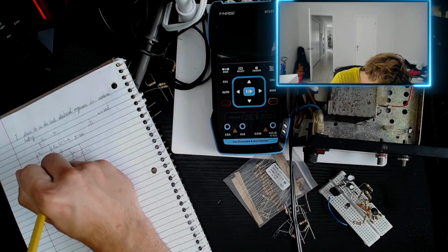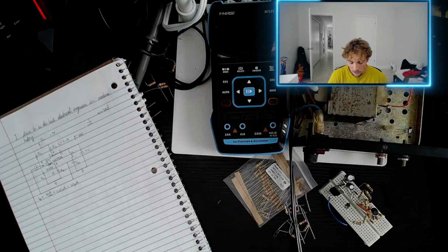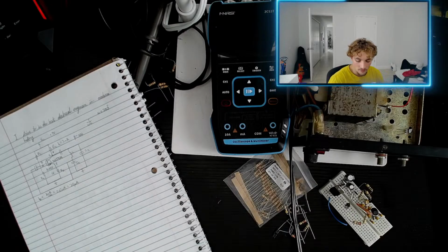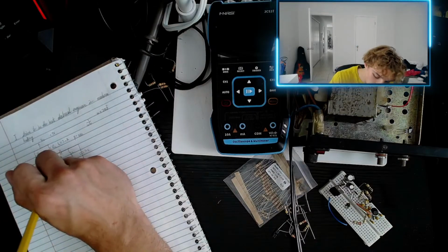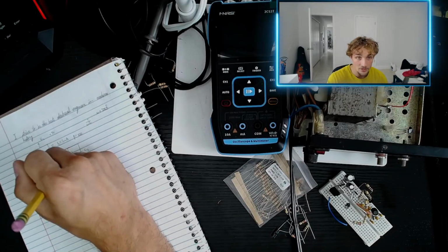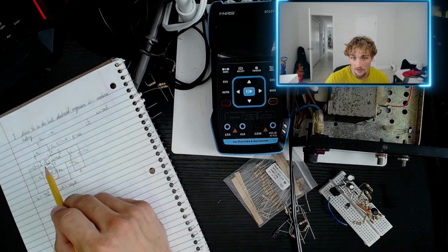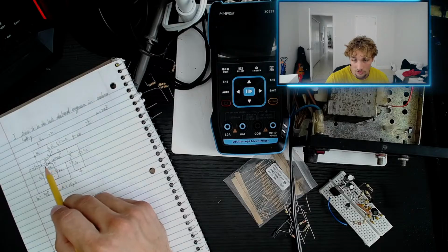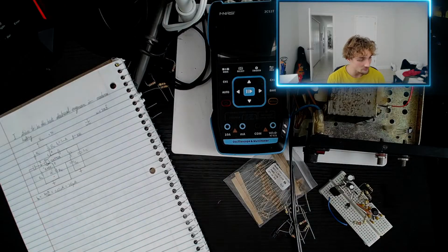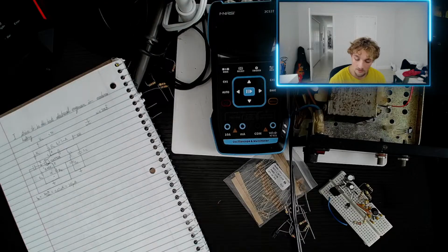Now, this reason I haven't fully come to a conclusion on. I don't know exactly why we want 1 volt here, but as we do our calculation, we might come to an understanding. So that's another assumption we want to make, is that we have 1 volt across the emitter resistor, right? So positive, negative here. We're having current flow in this direction. This is our emitter resistor, and our voltage across the base to emitter across our transistor is going to assume a value of 0.65 volts as long as we're operating in the active region or in saturation. Okay, and therefore we are, right? We want to set it up for saturation.